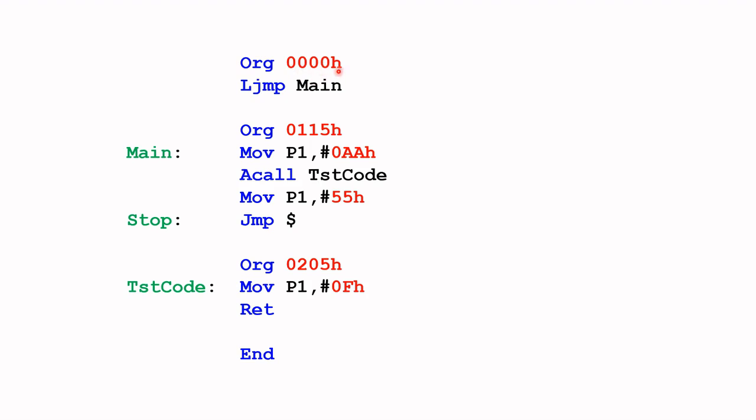And that's why you will see in some textbooks and code for the 8051, they do not bother to put this in, because the assembler will automatically place your code at this address, because that's where the 8051 expects to see your code starting point. Now, in this example, I've put at 0000 hexa this instruction ljump main, and basically when we